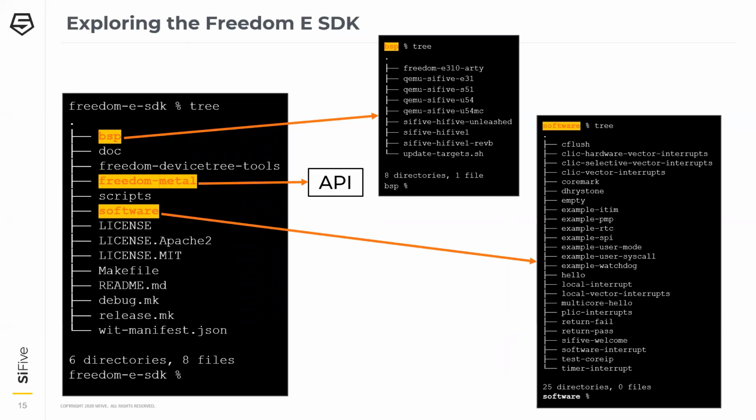Now, the BSP directory may look a bit different if you clone from GitHub. And I say clone because there are a lot of submodules, so downloading a zip from GitHub doesn't expand everything that you need. Versus when you download the IP delivery from SiFive Core Designer, this will be a trimmed and focused deliverable specifically for the core that you designed or selected.